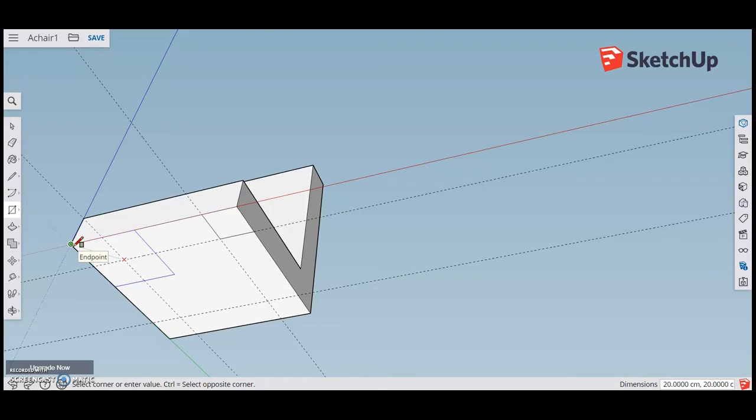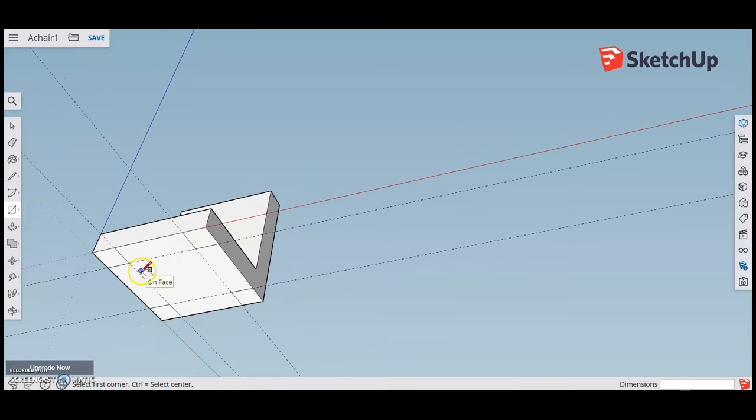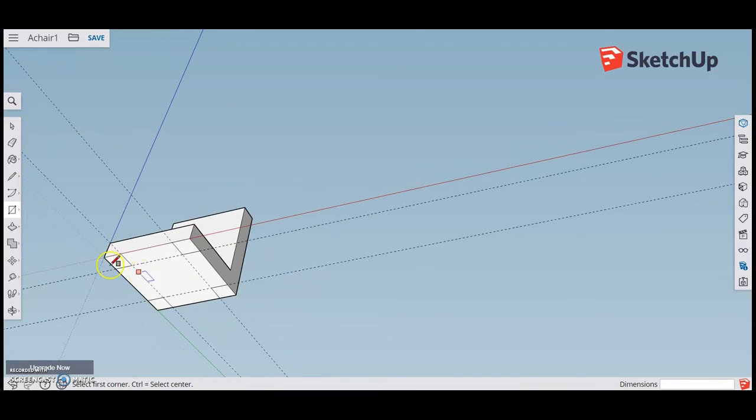And you can see from this perspective too, another problem has happened. You can see that our square is being drawn from its center rather than the corner, which we were working with before. And that's a default of the program. You can easily get around that if you just click to another tool, like the selection tool, and then click again on your rectangle. So we're going to draw our 3 other leg shapes very quickly here. And you'll see they're snapping right to the existing guides that we were working with. Now we have 4 equidistant, equal squares